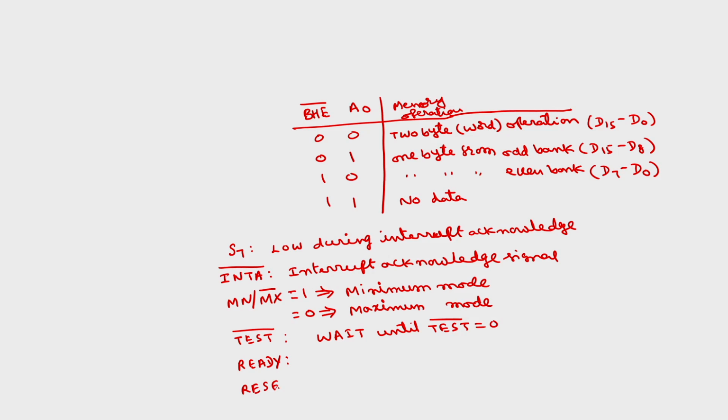Whenever the microprocessor is reset, it will suspend all internal operations. It will make the stack segment, data segment, extra segment, instruction pointer and flags 0, and the code segment FFFFH. Whenever this reset is removed, the next instruction to be fetched will be from FFFF0H, which we have already discussed in the last class.